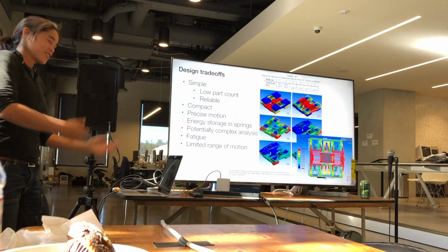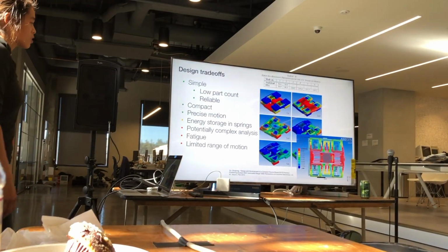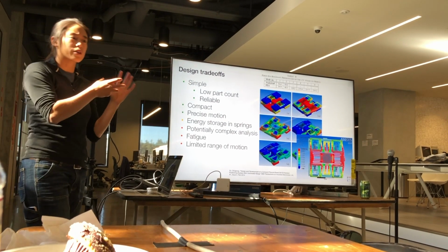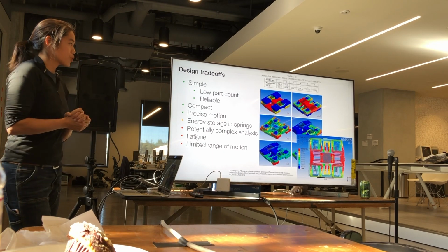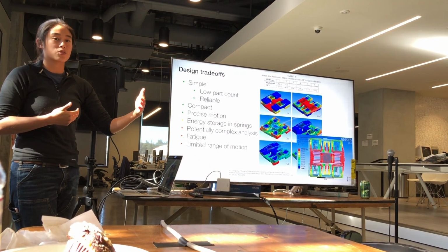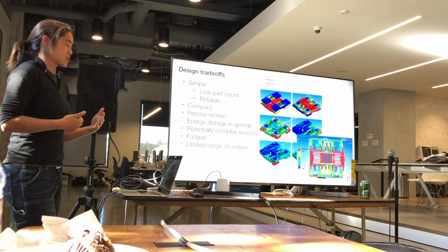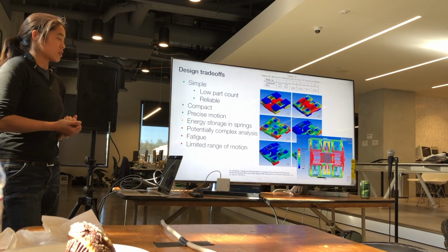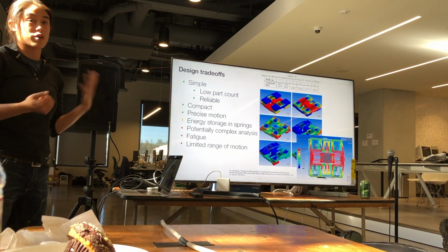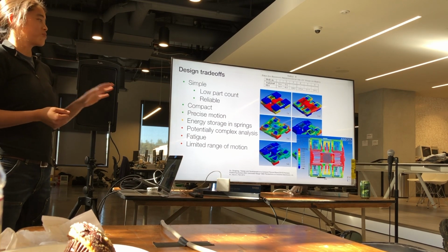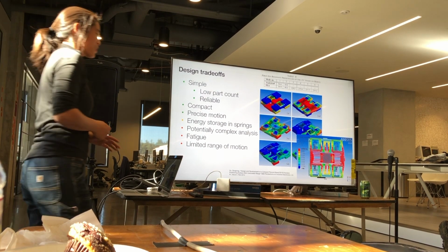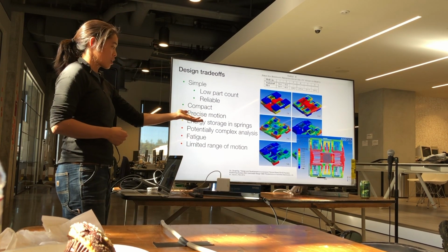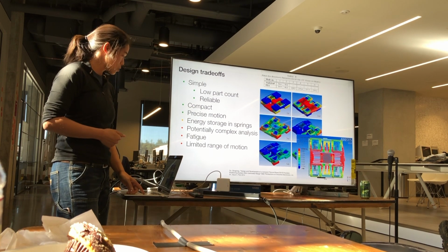Okay, so there are downsides to flexures. You can imagine that if you had a really complicated flexure, like that satellite thruster example, or if you were going to push a material to its property limits, or if you wanted a flexure that's going to last many, many cycles, then you might have to do some pretty complicated simulation work in order to verify that that's the case. I do basically no simulation in any of my personal projects, so it's all guess and check, trial and error. So yeah, that can be quite a burden for designing flexures.